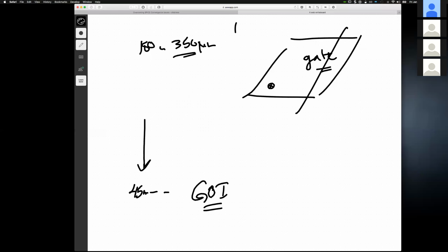I'm just maybe dividing the device. Maybe if it doesn't impact you with parasitic effects, adding more dividing transistors onto fingers, is that a better thing or not? You tend to make the design more robust by making judgments like these if you don't know for sure that it's an open-ended thing. But as Tim said, for a process like 350, no.